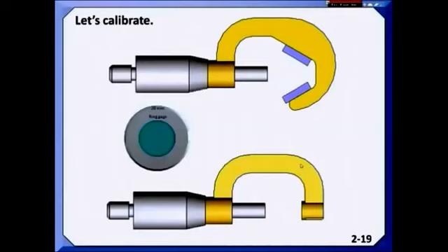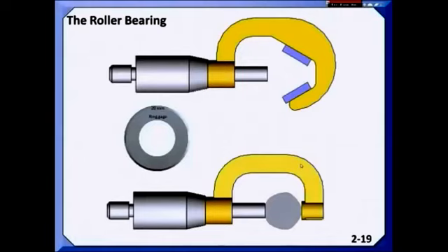This is an overlay that the students have that they get to work with, and first we calibrate our ring gauge at 20 millimeters and our anvil mic and our 2-point micrometer. We then bring in that 5-lobe part, which is very common in centerless grinding, 5 and 7-lobe parts, even 3. And we show how, no matter how you mic that bearing, you could not detect the lobing effect. And even if you put it in the anvil mic or tri-mic, as you rotate it, the mic would not change. But if they had followed Rule 1 and checked the perfect form at the maximum material condition, they would have found that that had a lobing problem.